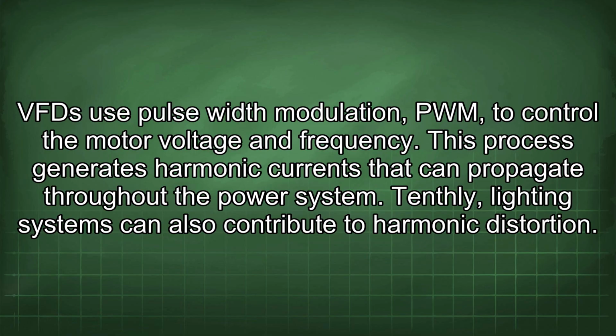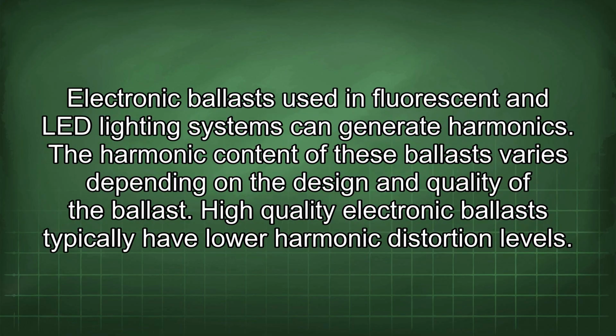Tenthly, lighting systems can also contribute to harmonic distortion. Electronic ballasts used in fluorescent and LED lighting systems can generate harmonics. The harmonic content of these ballasts varies depending on the design and quality of the ballast. High-quality electronic ballasts typically have lower harmonic distortion levels.